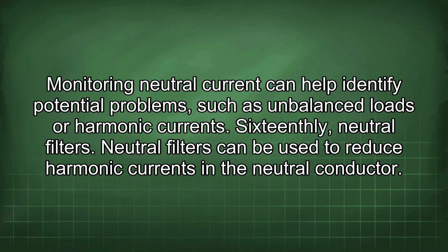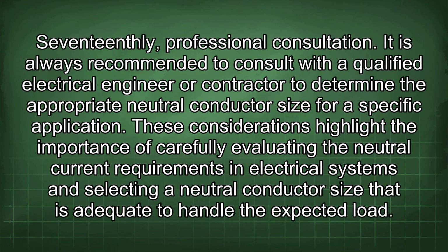16thly, neutral filters. Neutral filters can be used to reduce harmonic currents in the neutral conductor. 17thly, professional consultation. It is always recommended to consult with a qualified electrical engineer or contractor to determine the appropriate neutral conductor size for a specific application. These considerations highlight the importance of carefully evaluating the neutral current requirements in electrical systems and selecting a neutral conductor size that is adequate to handle the expected load.